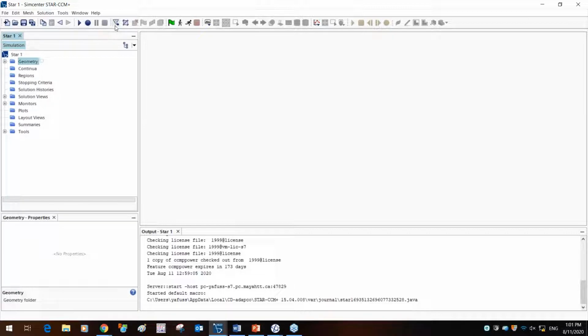The next section in the feature tree would be mesh generation options. So importing some mesh, launching the repair tool, as well as generating the surface and volumetric mesh. Then we have the run options. The green flag is to initialize the solution. Step is to move a given time step or iteration, and then run is for running the simulation, and stop is for stopping the simulation.